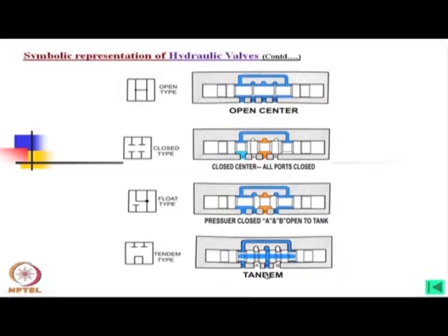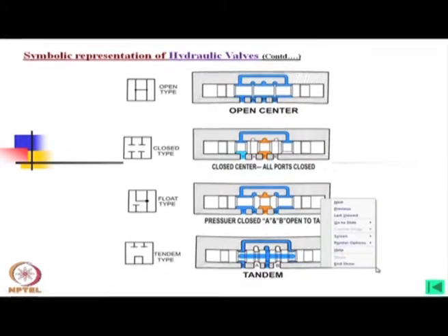However, the cost of this tandem valve is more. If you look into the spool, you can see inside the spool there is a hole, and through this hole oil has to pass, there is no other way. So, the cost of this tandem valve is more in comparison to the closed type or fully open type. Now, here we have only mentioned that this can be moved, we have not discussed how it can be moved.